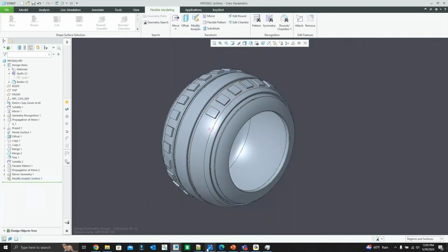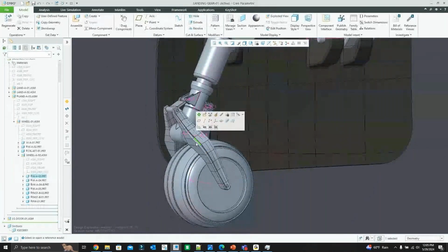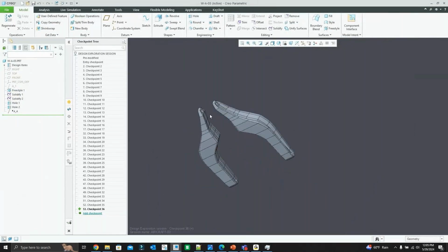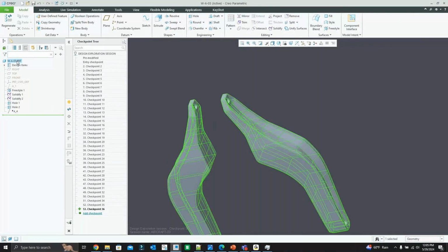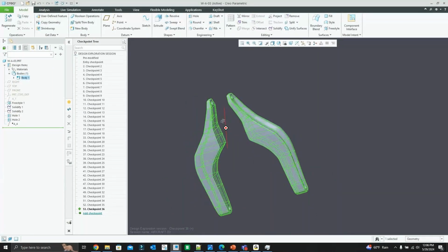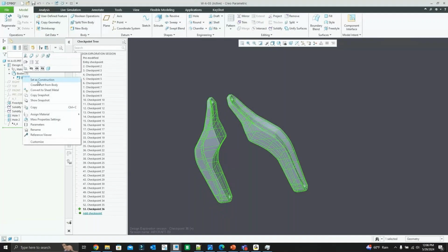All right. So let me move to a different part. So let's go back here, and I'm going to select this guy. All right. So we are creating a concept of the landing gear. We really don't need, we just need one of these. So this part is all one body. It really shouldn't be that, that's not good practice to have these two in here. So maybe what I'm going to do is create a part from body.